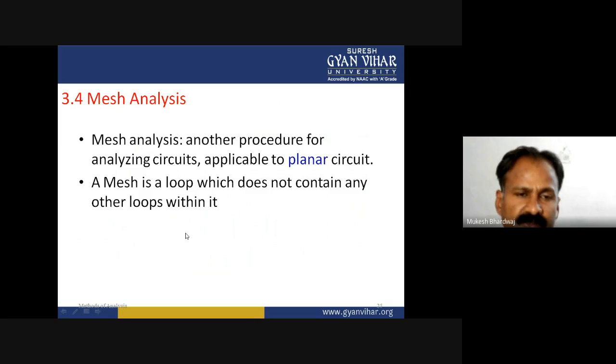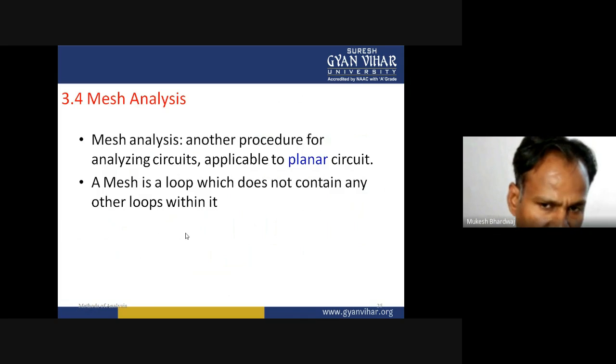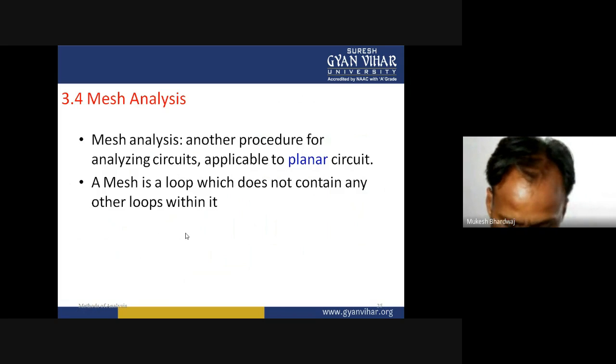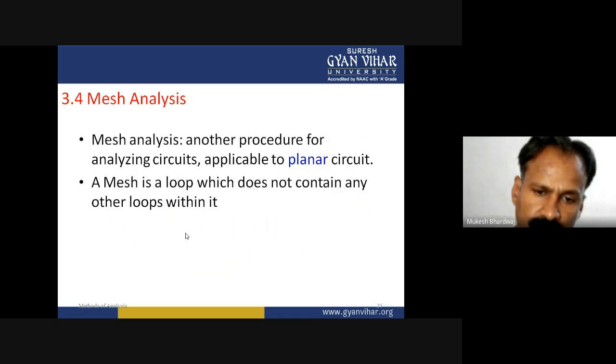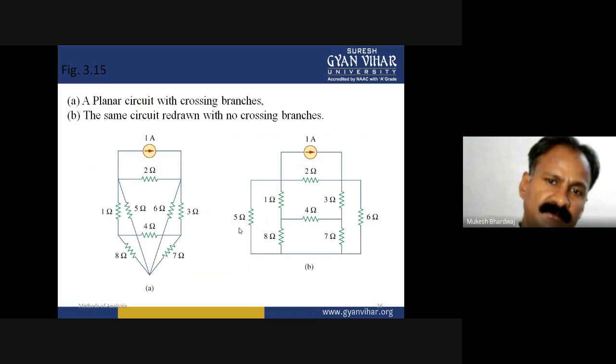Now mesh analysis, or loop analysis, or loop law, or KVL. Mesh analysis is another procedure for analyzing circuits, applicable to planar circuits. A mesh is a loop which does not contain any other loop within it. A planar circuit with crossing branches. The same circuit redrawn with no crossing branches.